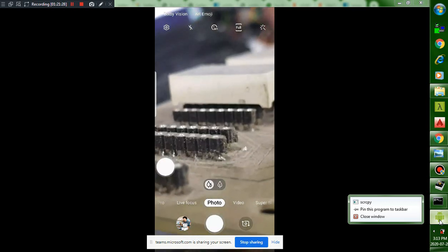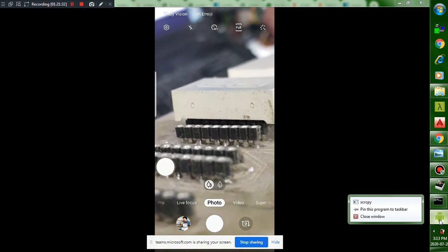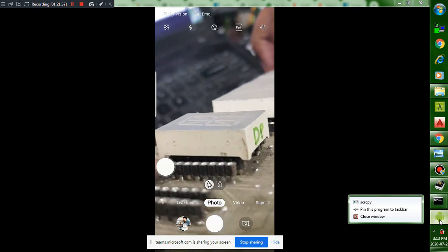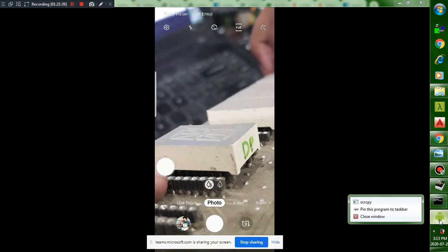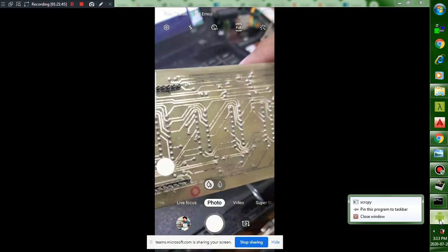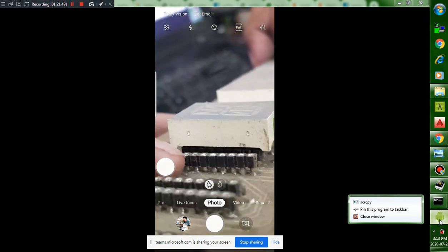But the advantage it gives us is that it can be soldered from the top side also, and it's a little difficult over here to solder it. As you can see, putting a soldering iron at that point, you can melt the plastic and all that stuff, but otherwise from the bottom it can be soldered down very easily. But at the other side, it's a little difficult, but it can be done. Not that difficult over there.